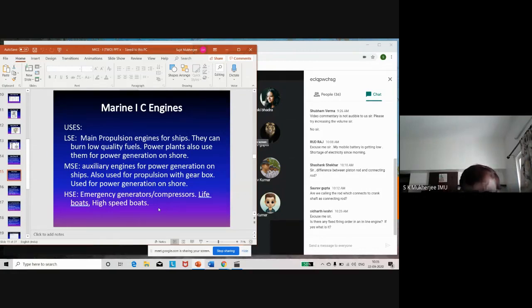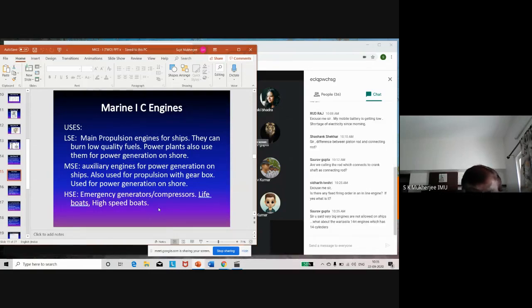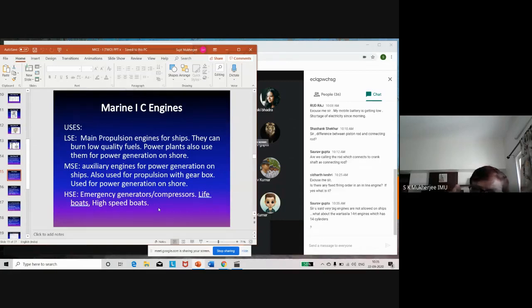A diesel-electric ship will have multiple medium-speed engines, maybe 6, maybe 8, but all of them are generating only electricity. That electrical power which is available is ultimately used for everything: your lighting, air conditioning, running pumps, whatever there, including running your propeller. So those are diesel-electric ships. Your propeller is run by a synchronous electrical motor, and control is very, very smooth and almost to perfection.